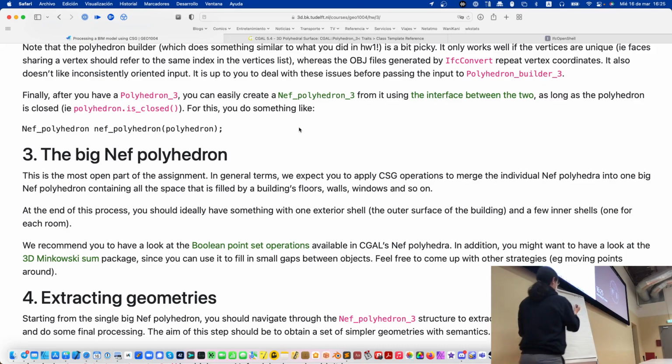So let's say that instead of A and B, this is 1 and 2, and this is 3 and 4, in an OBJ file. If you find something that says 1, 2, then you should find 2, 1. You should never find 1, 2 and also 1, 2 in a different face. That's how you can check that these are correctly oriented.